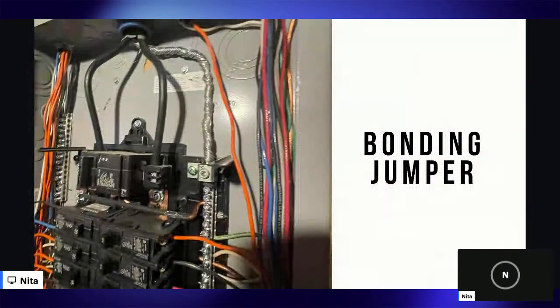All right. A bonding jumper. This copper strap right here is called the bonding jumper. It is basically a metal connection that's inside our main panel that connects the neutral to the ground. So remember, in a main panel, we can have these connected. In a sub panel, you cannot.